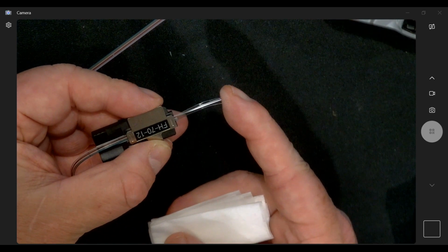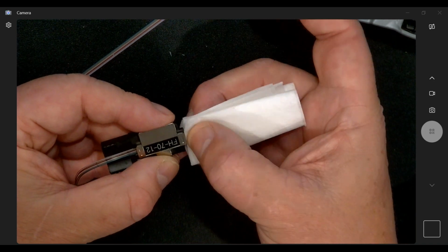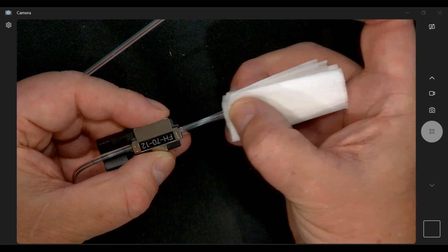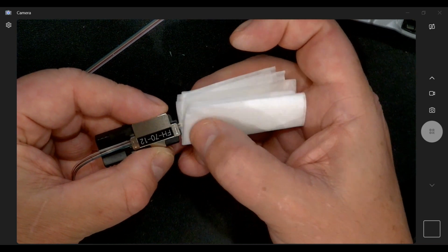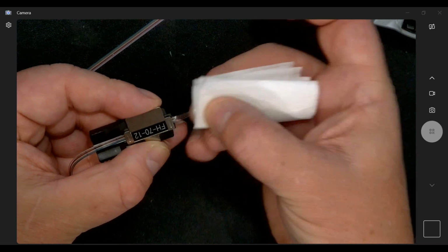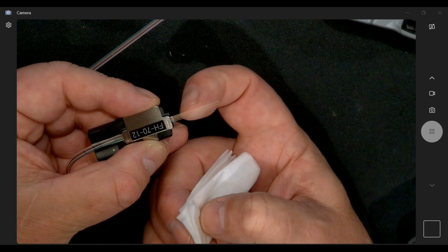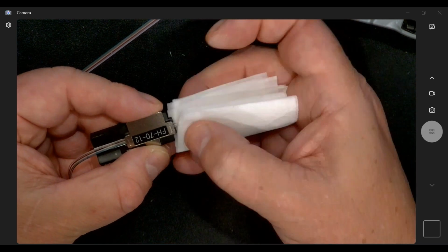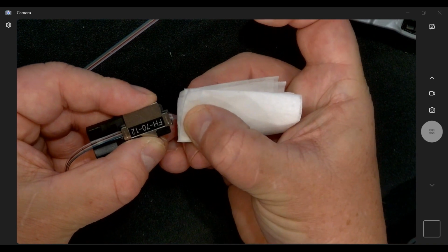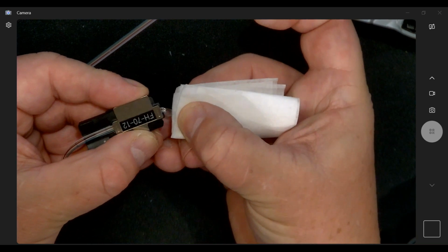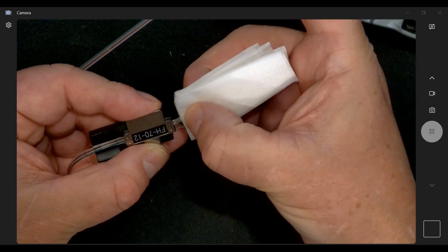Now this ribbon, if I have any issues with it, I will use my cleaning mechanism to pull the fibers in position. So if I notice that fiber number 11 and 12 were protruding downward, I would have no problem taking this wipe and pulling that fiber at a high angle to get this fiber to come into the right position.